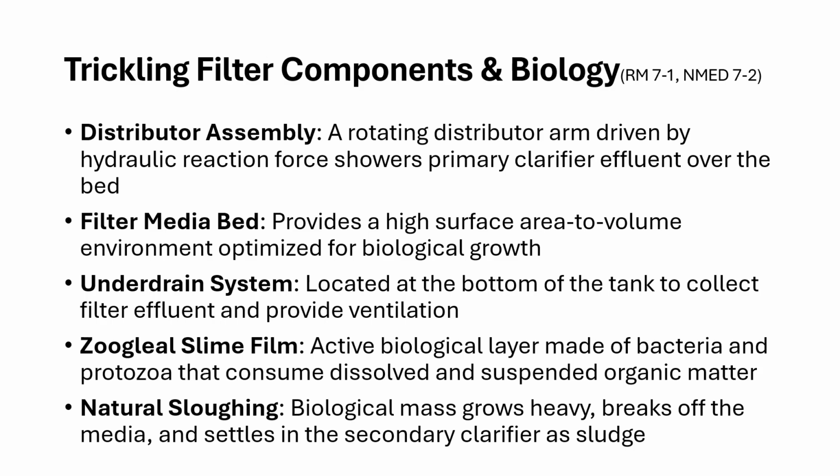If we had a high pressure stream of primary clarifier effluent entering the trickling filter and spraying out over our filter bed, we would wash away that slime layer and we wouldn't do ourselves any good. So that's why the name trickling filter comes about, because that's what you're looking at for a flow rate. It's going to trickle out rather than shower or spray out at a high pressure.